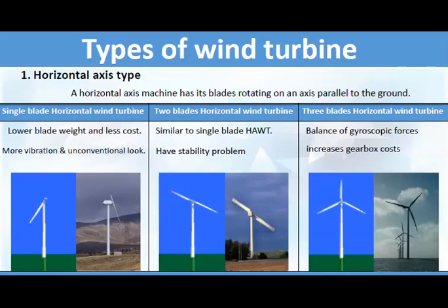Large three-blade horizontal axis wind turbines with the blades upwind of the tower produce the overwhelming majority of the wind power in the world today. These turbines have the main rotor shaft and electrical generator at the top of the tower and must be pointed into the wind. Small turbines are pointed by a simple wind vane, while large turbines generally use a wind sensor coupled with a yaw system.